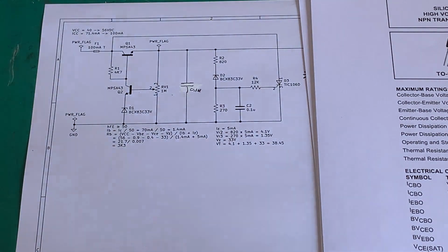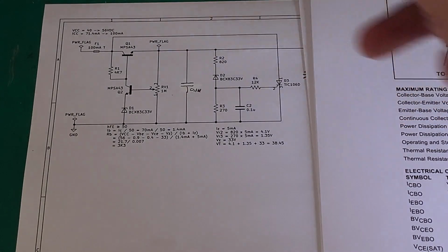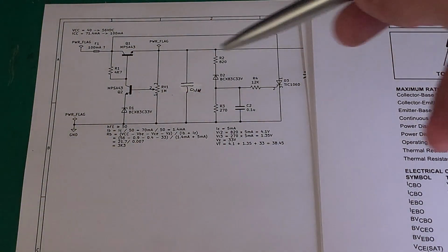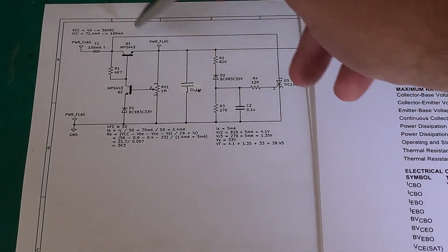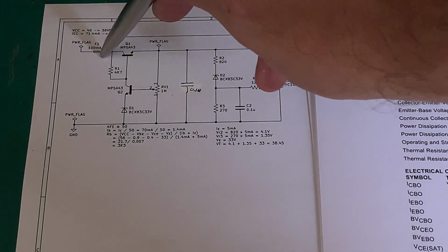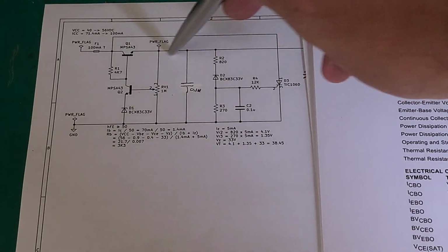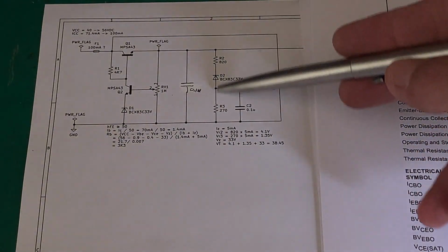That doesn't help us much, because what happens when, or if, that transistor blows? In my experience, and in general, when these semiconductors go, these transistors, they fail short. And if they fail short, that means the voltage that is here is going to be the voltage that is here. And we will destroy everything downstream. So what we can do is we can use this circuit.